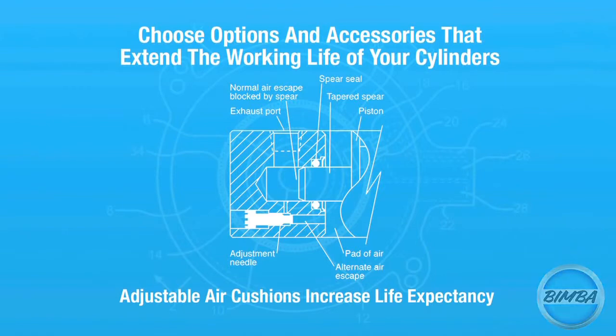Stop tubes, or dual pistons. These options are used to help reduce side loads by spreading out the distance between the rod bearing and the piston, thus reducing the effective loads at these 2 points.